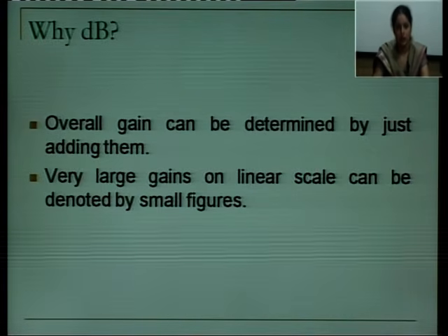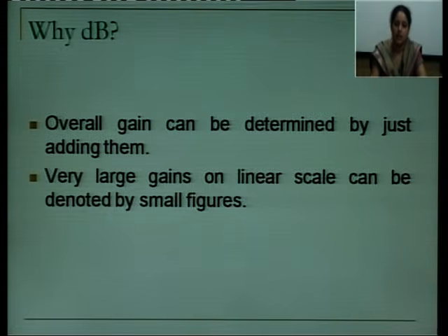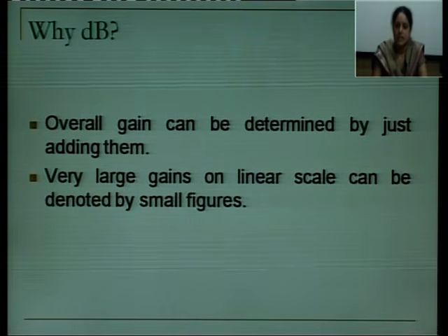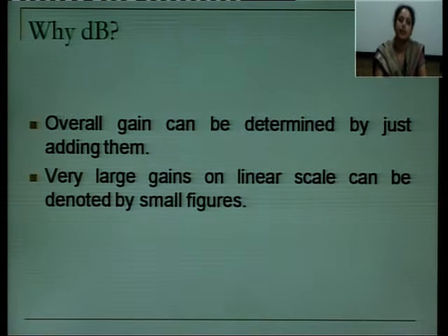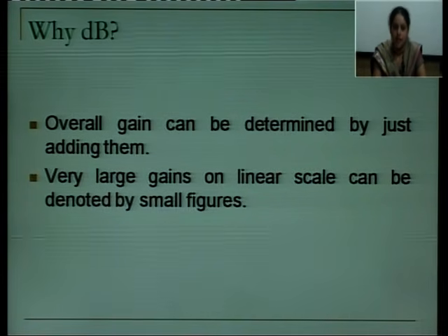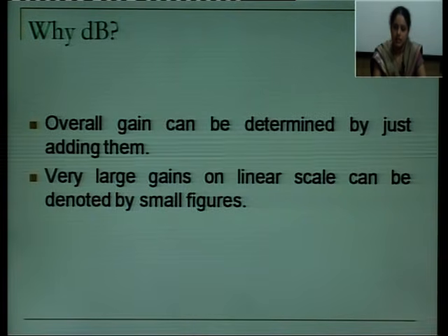Now why dB? Why are we considering units in dB, not in other simple units? Overall gain can be determined by just adding them. We have discussed that your amplifier gain is G1 into G2 into G3. For example, the gain of each of your 3 stages is 10.